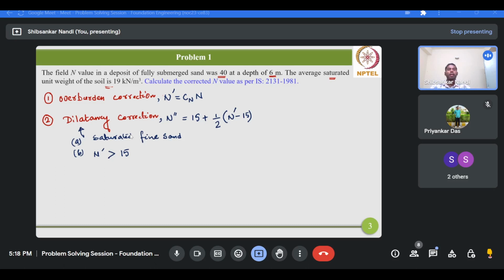So you will be basically expecting a different behavior for both the samples. First of all, as you increase the confining pressure, it will give you more resistance. So you will be observing more deviatoric stress.